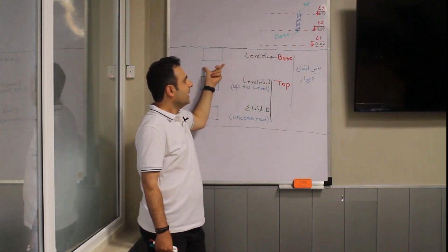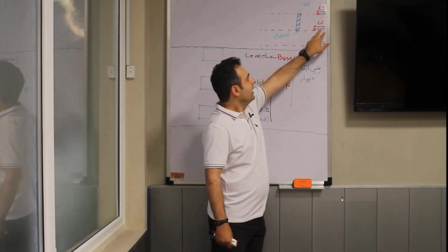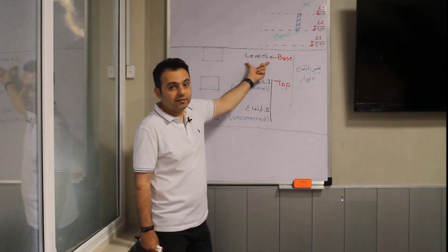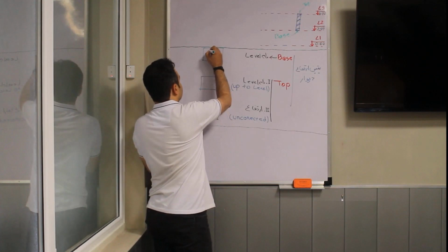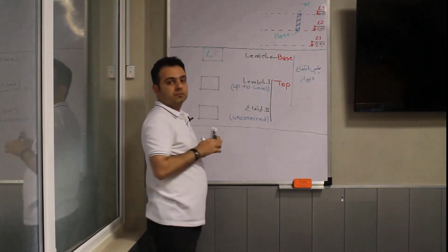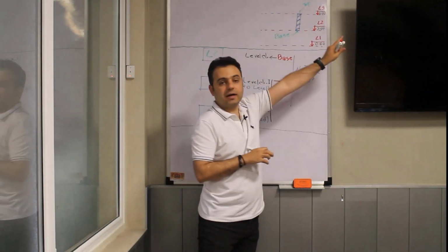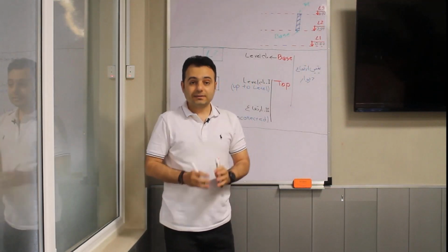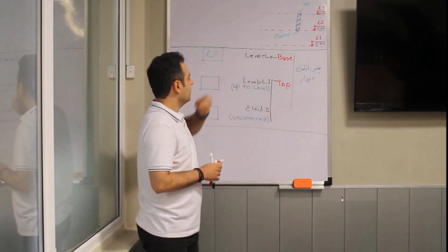If anyone is saying 3, well, it's wrong. But why? Because 3 is the height of this wall. Here I said it's determined by the name of the level. So what should I write here? That's right, it should be L2. You see, that means that the base of this wall is on level 2. So you understood that the base of the wall works with the level's name. And now we should say L2.